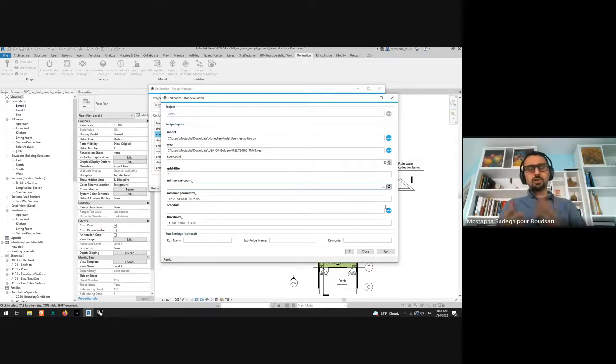So you should have a good number based on the data. 200 is fine for the inputs that we have. This is something we're trying to optimize, to give you better suggestions as you go. So the run name is user meetup Revit sample model. Now that I've said all this, I can do run. What it does is prepare this and start the run on the cloud.